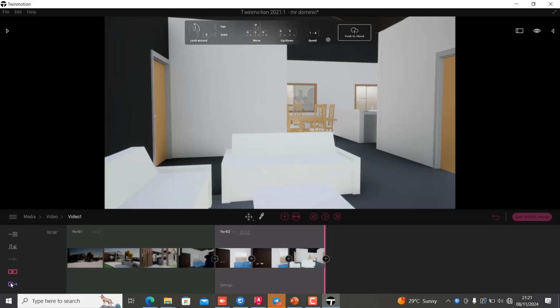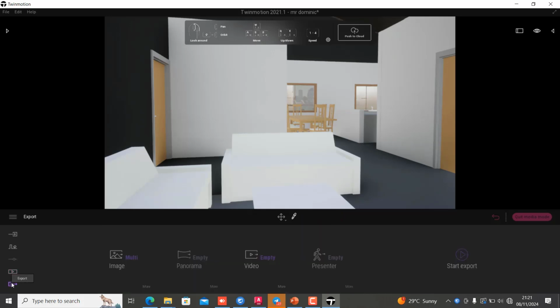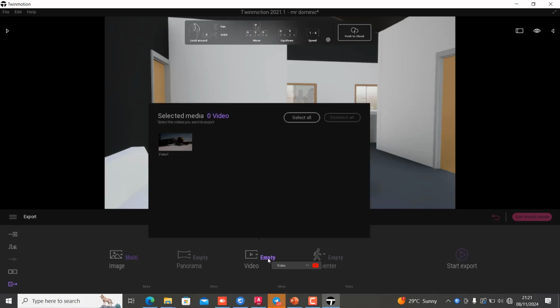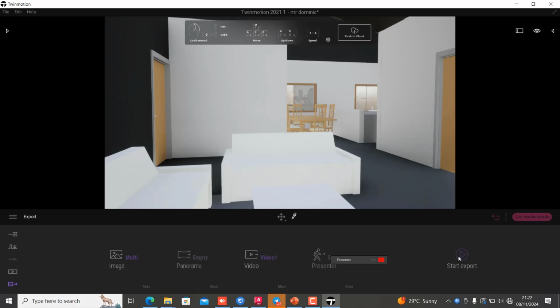After creating your walkthrough, all you need to do is come to your export. Once you click on export, and click on video here, it allows you to select. You can see this is the previous video we just created. Once I select this, I can click on start export. It will export the video just like you did for the image. It's the same thing. And then you just go to the directory where you sent the file to view it there.